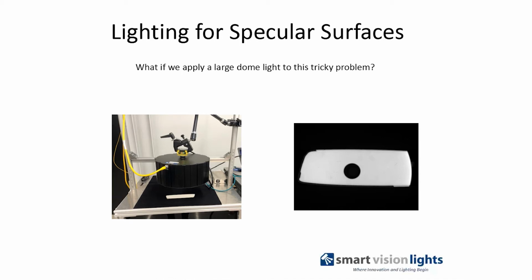Well, as when we were talking about this in the bright field presentation, this works really good, and you can see this works because you're bouncing off the inside of the dome. You're still imaging with very direct angles, but light is coming off the inside of the dome at all angles and striking very uniformly on the surface. This works because the surface becomes very bright, white, and uniform like the inside of the dome, and you're actually lighting up the surface uniformly with the reflection, taking advantage that we can make a very even reflection of the whole surface and get things flat and uniform.